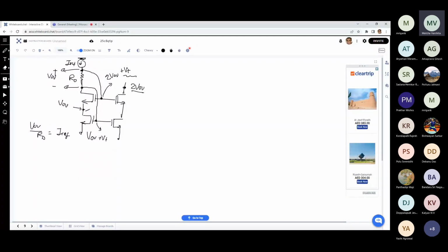So this is a good current source and commonly used. We will discuss some other configurations also which are even better. For the time being, this is pretty standard. Whenever you need a very good current source, very high impedance, it has its effect; a good current source is also very important for differential circuits. Those things we will study a little later. But both simple as well as cascode current source you should be comfortable with.